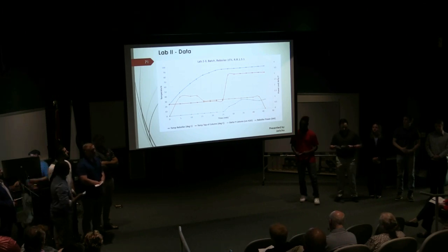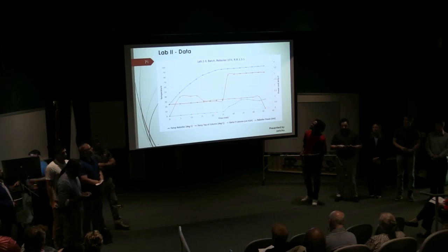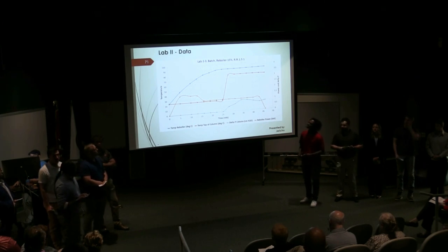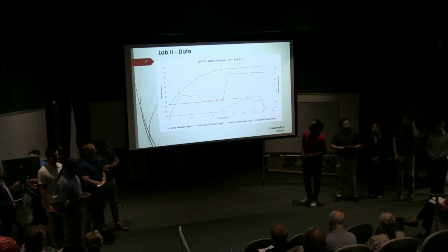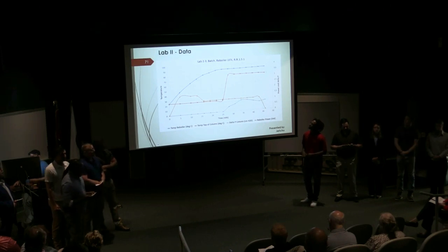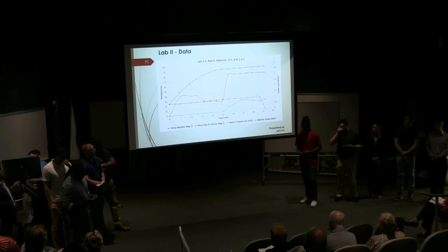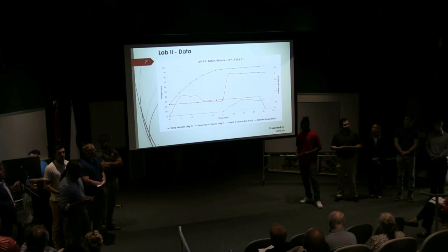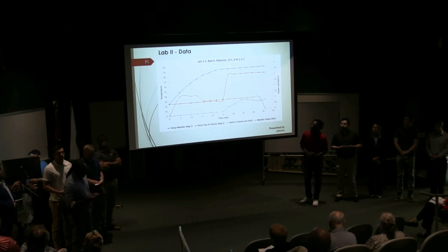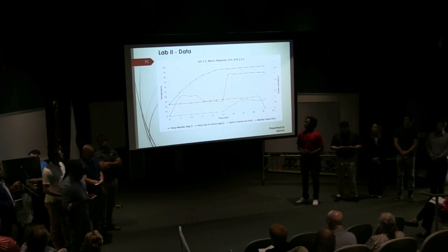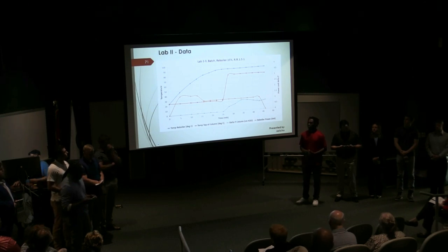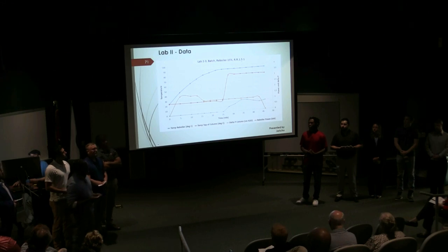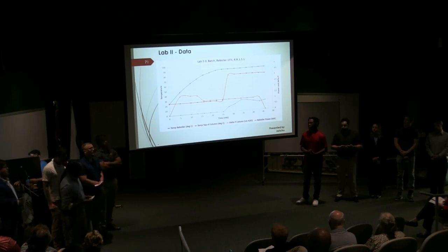In our final experiment for lab 2, we see that the reflux ratio is now 1.5 to 1, giving us another stable run. Plots indicate no adjustment to the reboiler was needed. Our delta P measurements are similar to the second experiment. However, some of the pressure drop was higher due to fouling, or what I should say, local flooding at the top of our column. This is from reflux ratio, causing what we expected to see, a decline in production.